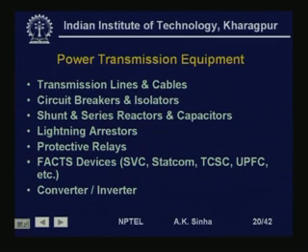Some of the devices which we use are SVC, the static voltage, static var compensator or static var controller systems, STATCOM, static compensator systems, TCSC, that is thyristor controlled series capacitors, UPFC, unified power flow controllers, etc. For HVDC transmission system, we need converters and inverters at the two sides.